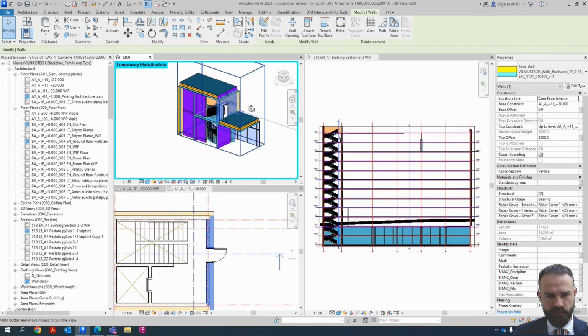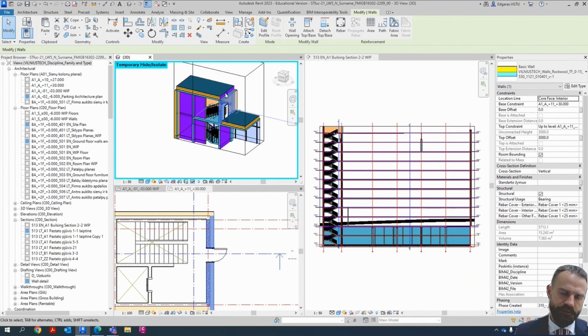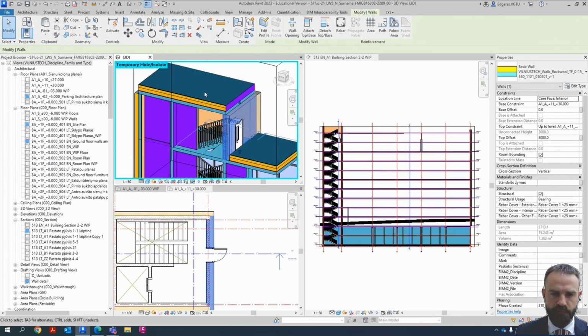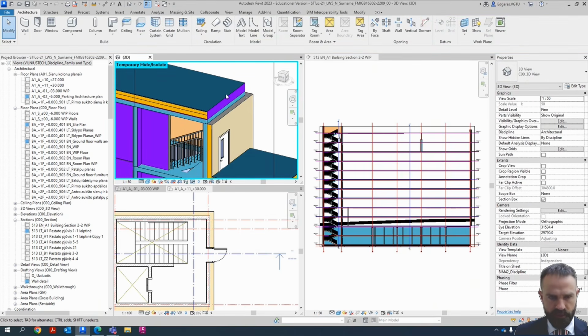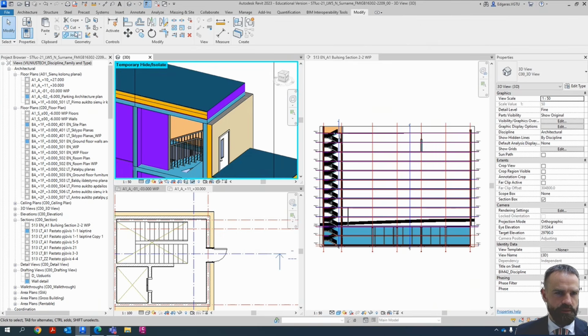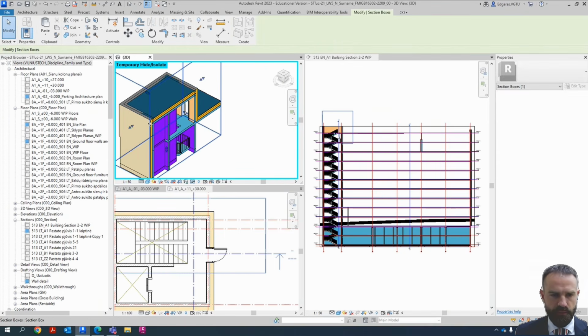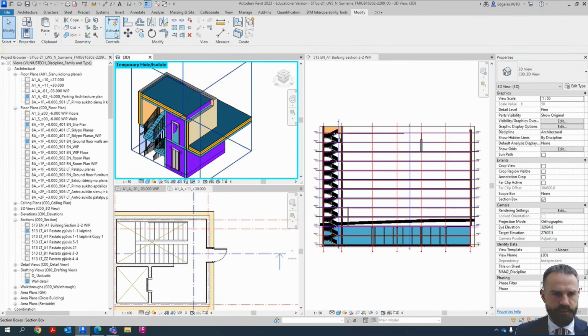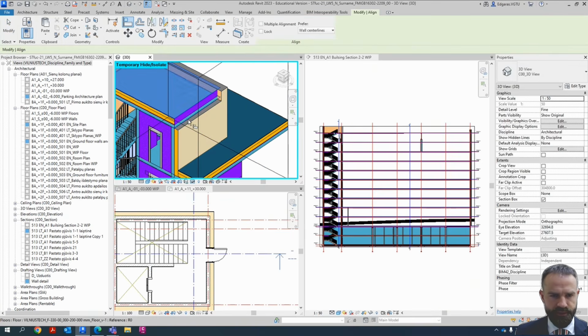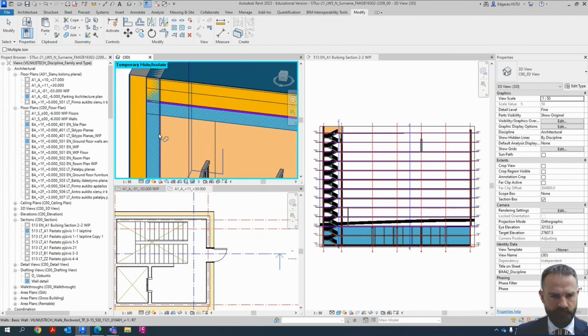Exit to the roof room. Also I think I should create the parapet part, but in this case I will just use the align tool and extend my walls up to the top. If I want to create a parapet, I can use the same technique I showed in other lectures. In this case I will just align this wall, use the join tool, and join the main component.